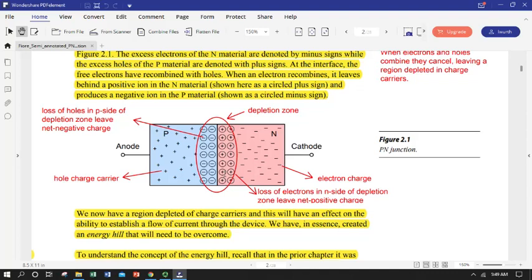And in fact, if you think about a capacitor, it has its own voltage if you pile charge on it. The interface of a PN junction is a little tiny capacitor that has a fixed amount of charge, so it's got a fixed voltage associated with it in a circuit. And we are going to leverage that fact when we put these in circuits.